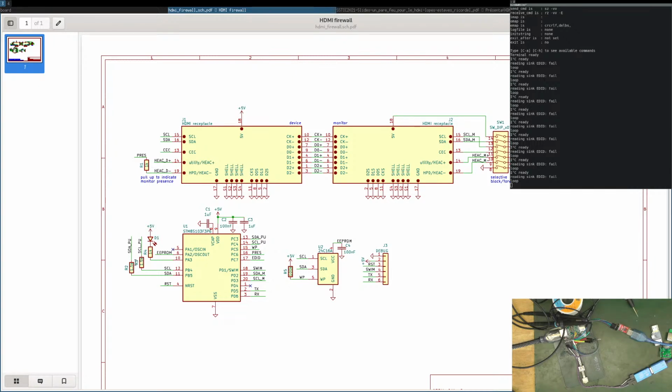I need to have pull-ups on the other side. Do I plug here? How do I do it? I don't pull it up myself because I have these pull-ups, this pull-up signal, and so they don't crosstalk. I'm connecting to 2 pins and then I pull up on both sides. The problem is I don't... oh, I do. 1 and 2, I have 2 pins, so I can also pull up on the other side.